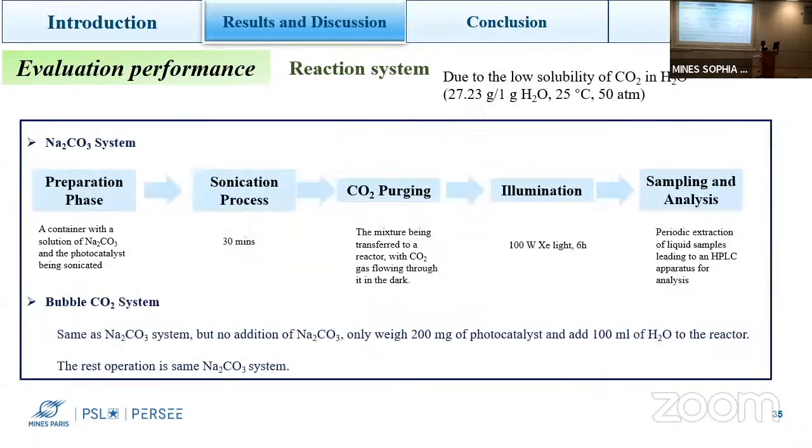And here we have to take care with our reaction system because the solubility of CO2 in water is really, really low. That's why the efficiency is quite low if using a pure water reaction. That's why we chose the sodium carbonate system.